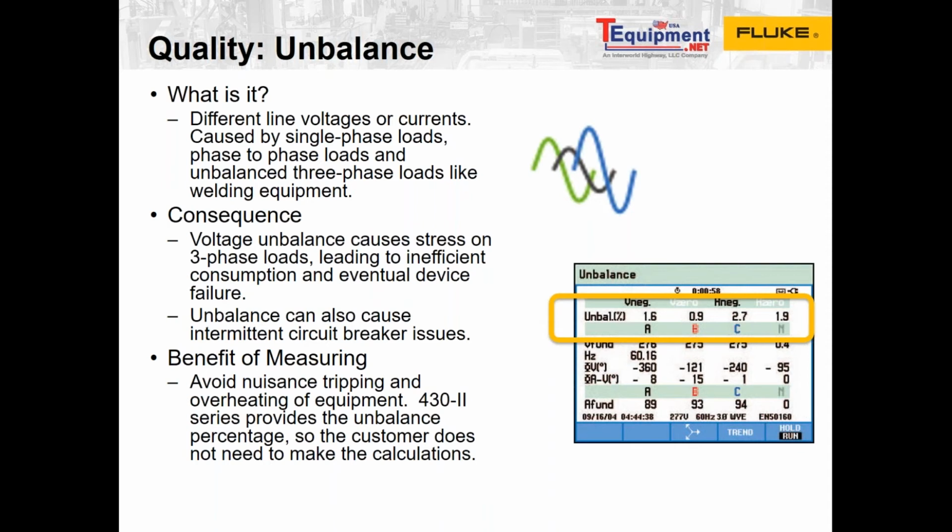And for every 1% voltage unbalance, motor current unbalance is 3% to 4%. So what that means is it's worse. So you'd want to check the conductors to see if the drive has failed, or if possible, power the motor directly by bypassing the drive to determine if the drive is a problem. And then this measurement rules out the motor overheating due to voltage unbalance, but it doesn't, on the other hand, rule out other overheating causes. So generally, current unbalance for 3-phase motors should not exceed 10%.